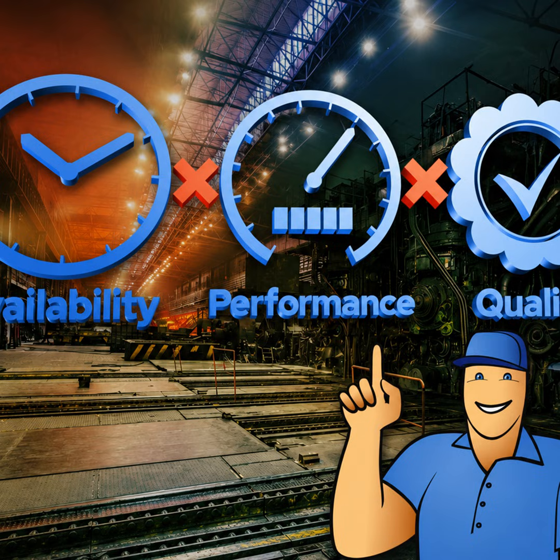Real-world OEE example. As you might guess, not every OEE calculation is as simple as that. When you add in the three pillars and potential 6 big losses, things can get more complex. Let's lay out a scenario that is more accurate for real manufacturing. Let's say you're running a 10-hour production shift. That means your potential production time is 600 minutes. You also have a scheduled break of 30 minutes, which makes your total planned production time 570 minutes.